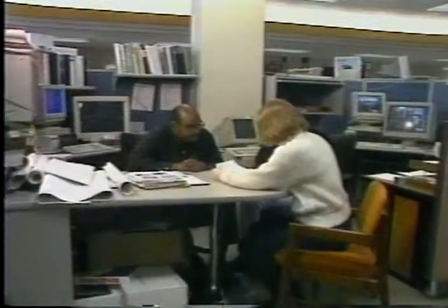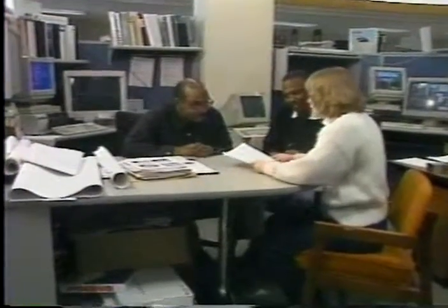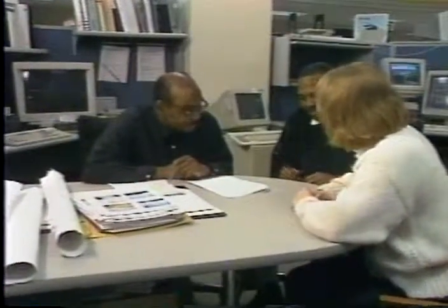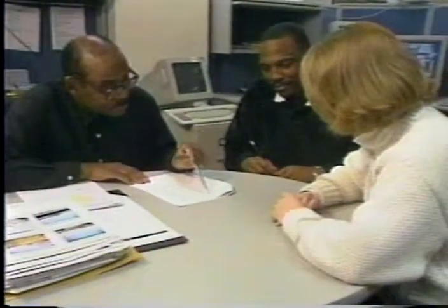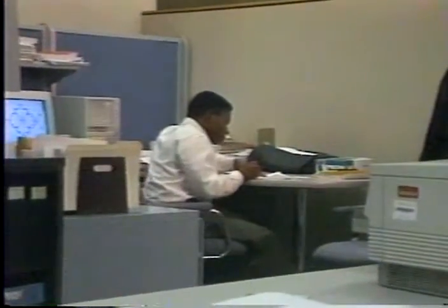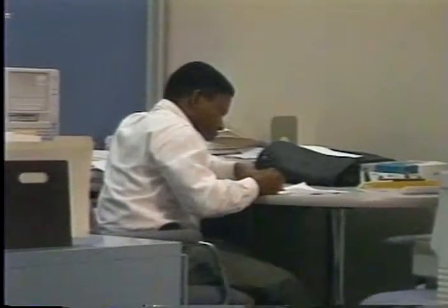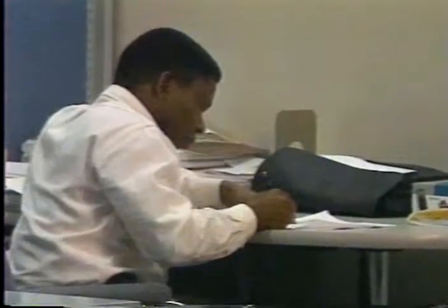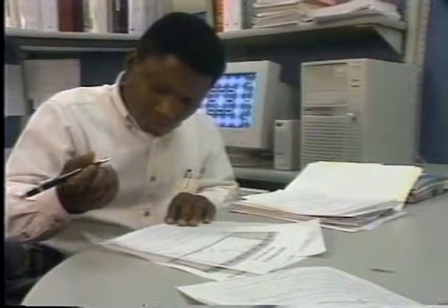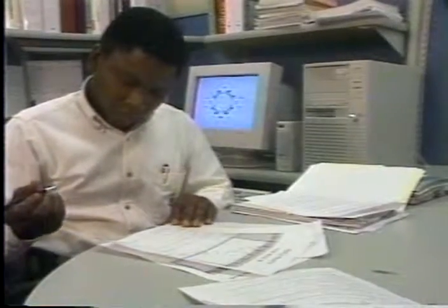A review of monthly manpower estimates helps in determining the need for seasonal personnel and the number of permanent personnel available for other work during the off-season. The use of planned overtime should be considered to meet peak construction needs. The advantages of using overtime include continuity of inspection and a smaller workforce during slack periods caused by bad weather.